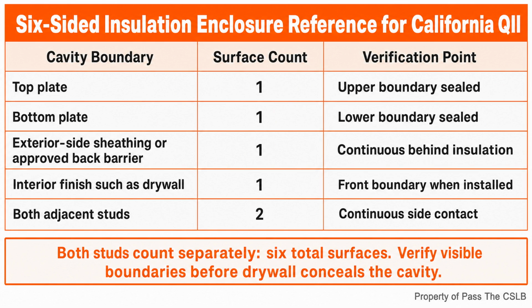The joints and penetrations in the building envelope must be caulked and gasketed or otherwise sealed to limit air movement. Filling an open chase with loose pieces of fiberglass does not create the required solid boundary. Imagine a contractor managing a vertical plumbing chase that connects an unconditioned lower space to an unconditioned attic. If the chase boundaries and pipe penetrations are left open, air has a route around the insulated assemblies.